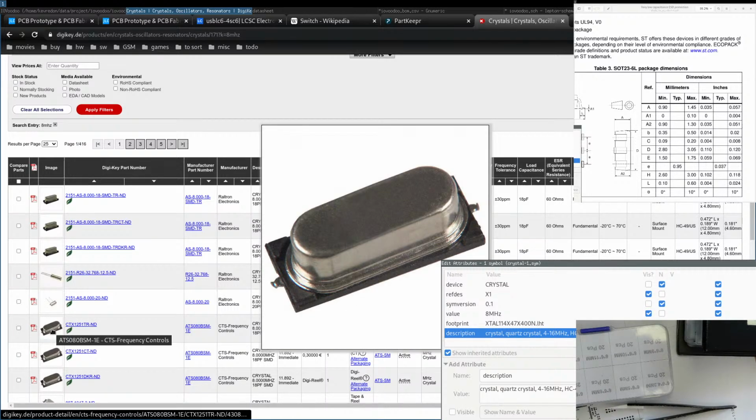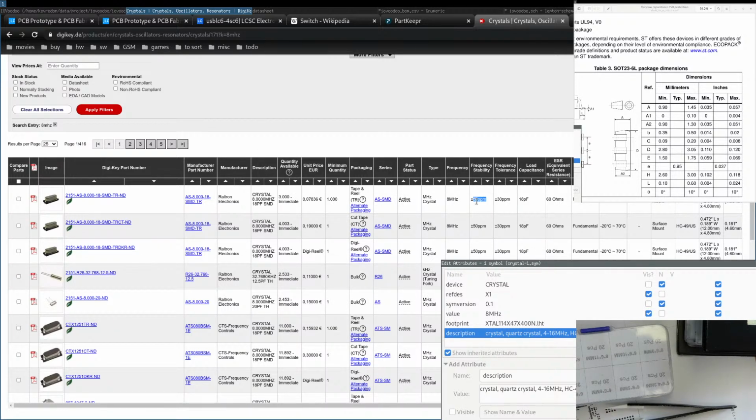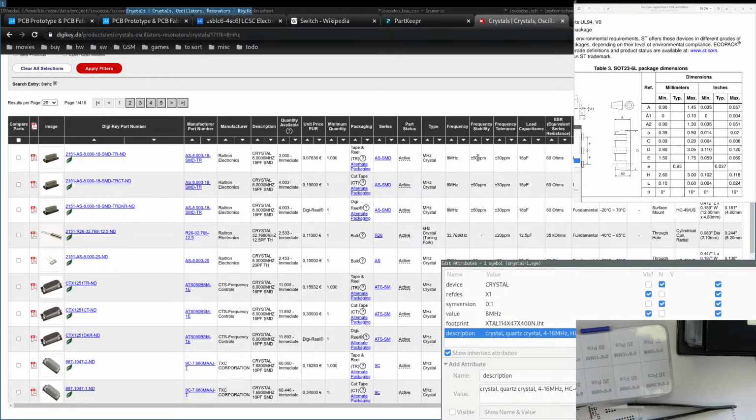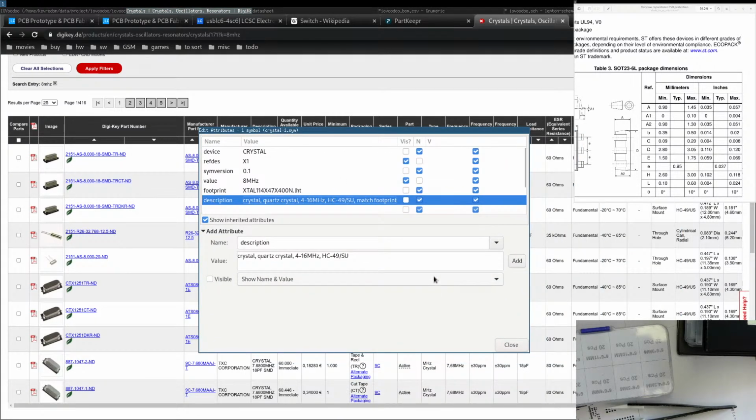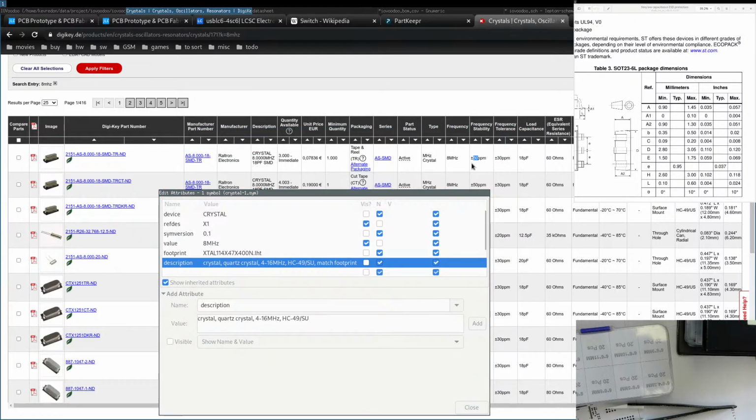So everything which fits here, and then what's important is the frequency stability or frequency tolerance. I could specify them here. They are all perfectly within the margin. They are better. So 50 parts per million is better than the 1% in the microcontroller, a lot better than the 1%. Very stable, and even the worst one has something like this.